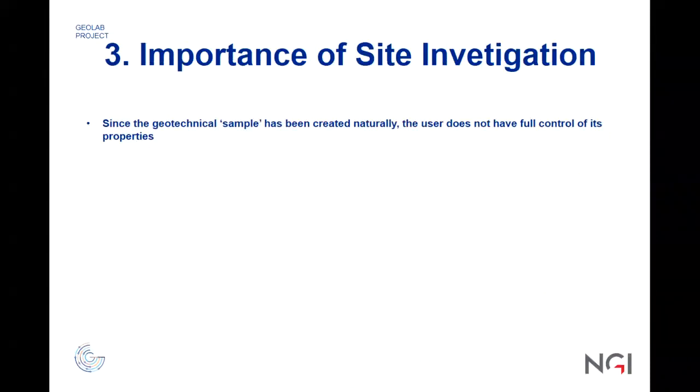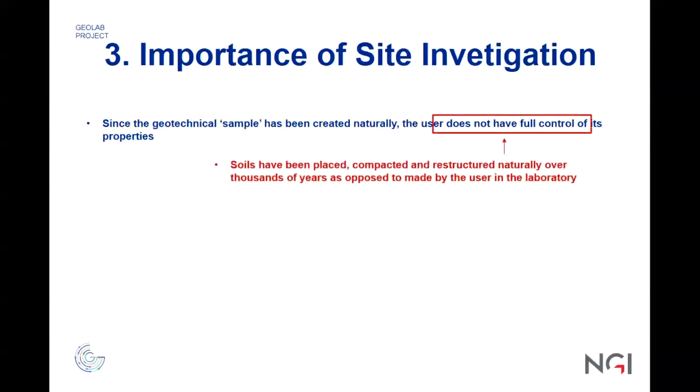Site investigation is very important, and it is important in reality when you actually, hopefully one day, work as a technical engineer. That is the first step, and it is a very important step, because it gives you information on what you are working with, what you are designing for. In this case of field testing, basically the sample has been created naturally, and we do not have full control of its properties, so we have to find out what it is.